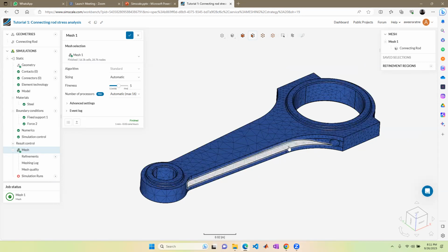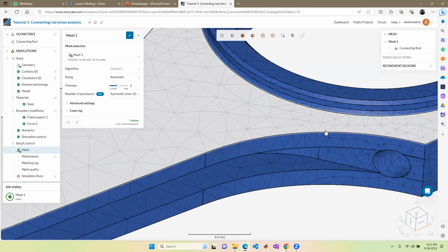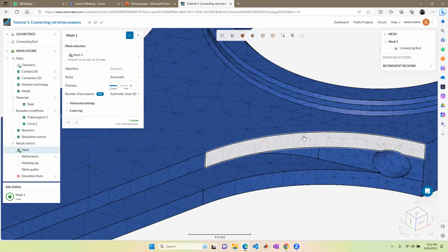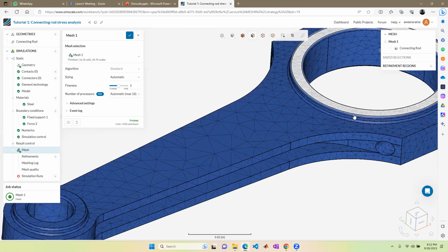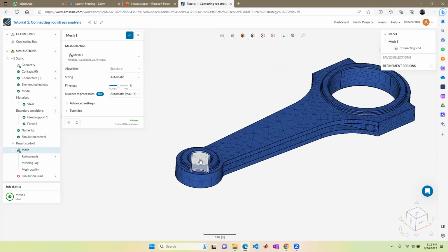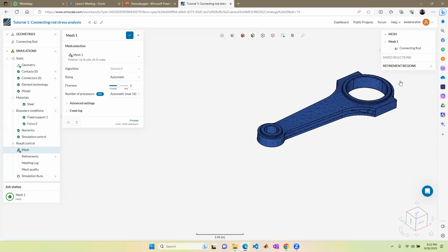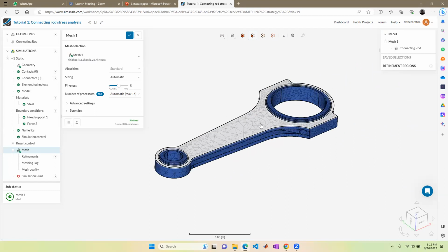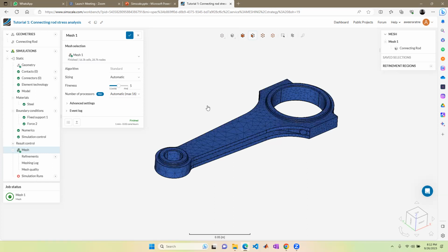A rule of thumb with regards to mesh refinements is that in areas where there are sudden or more drastic changes in the geometry, you would have to use more refined, relatively smaller cells, and also closer to the boundaries the mesh size has to be smaller. You'll come across more rules of thumb like that if you read textbooks with regards to FEA. That's up to you if you want to do it or not.